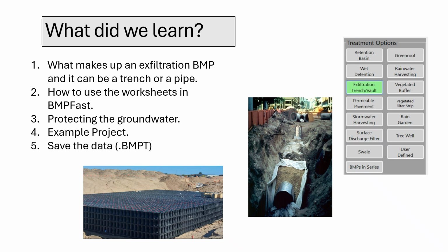We then moved on to practical application, learning how to effectively use the worksheets within the BMPFast software. This included calculating the average annual pollutant removal and demonstrating how an exfiltration system can be leveraged to meet even the most stringent performance standards, like a 95% removal rate.